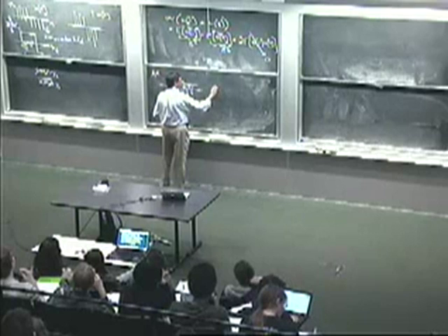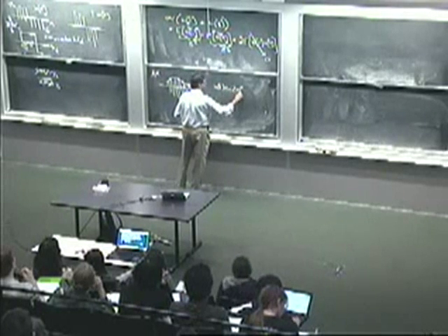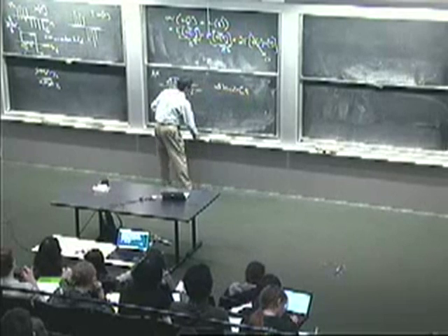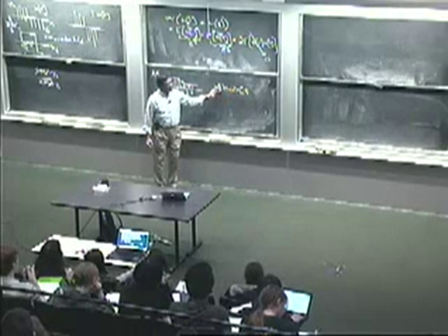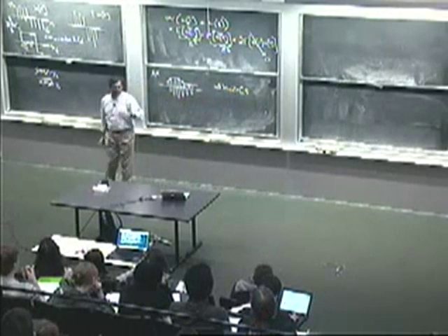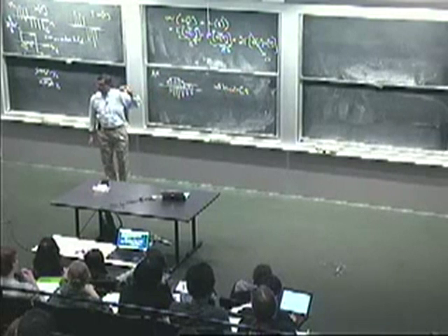So this would be something of the type x of t cosine 2 pi f_c t. All right, so it's a carrier, which is a pure cosine, and you have an amplitude that's slowly varying, and it's the amplitude that carries the information for the analog communication.